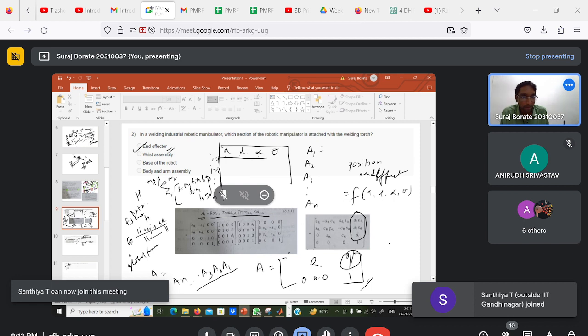The formula I showed you in the last question was where you were given the DH parameters and had to find the homogeneous matrix between 2 frames. So this is just the homogeneous matrix between just 2 frames. Now there are n links, so there are n frames. You just multiply all of these in order. Let me just check the order. Am I making some mistake over here?